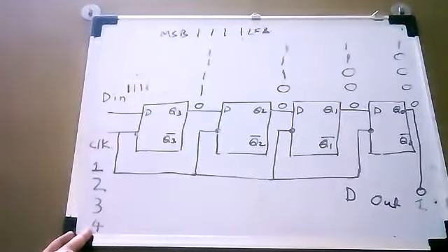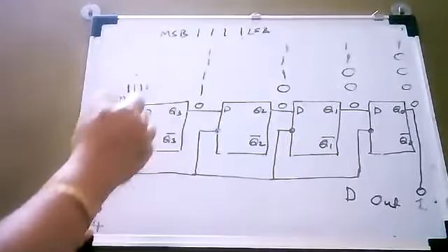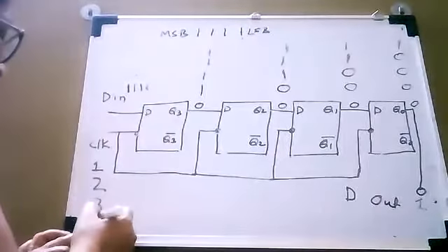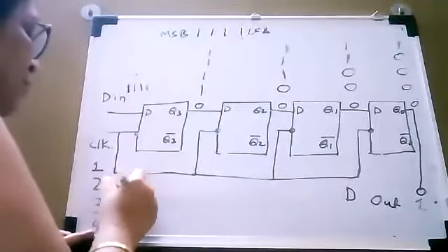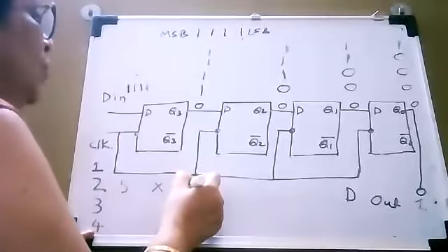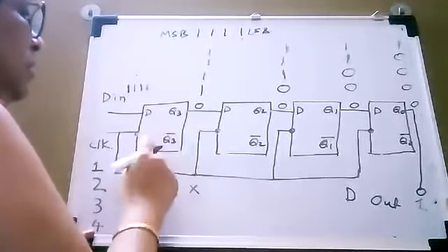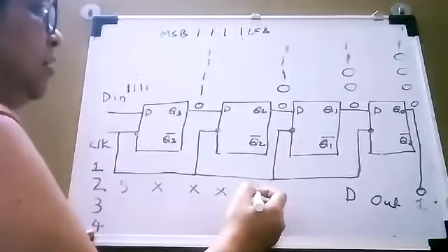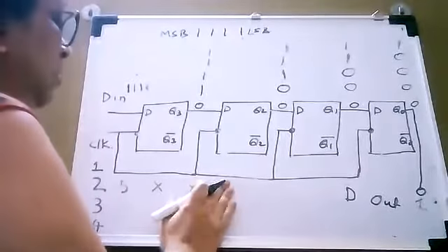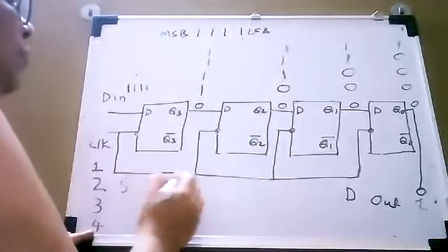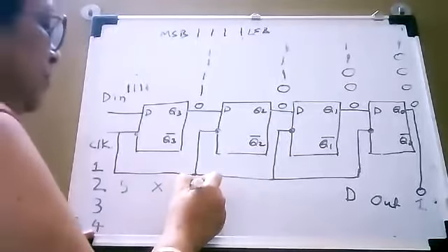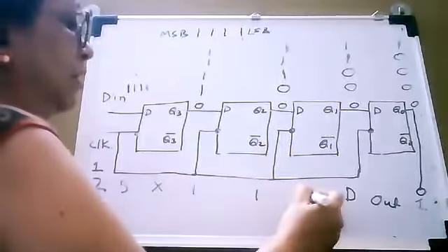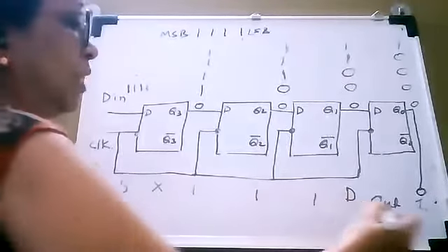And in order to output the remaining 3 bits, you have to apply 3 more clock pulses. Okay. So after applying 3 more clock pulses, after application of the fifth pulse, don't care about the output of the other flip-flops, the output of the third flip-flop and remaining flip-flops will be 1, 1, and 1.